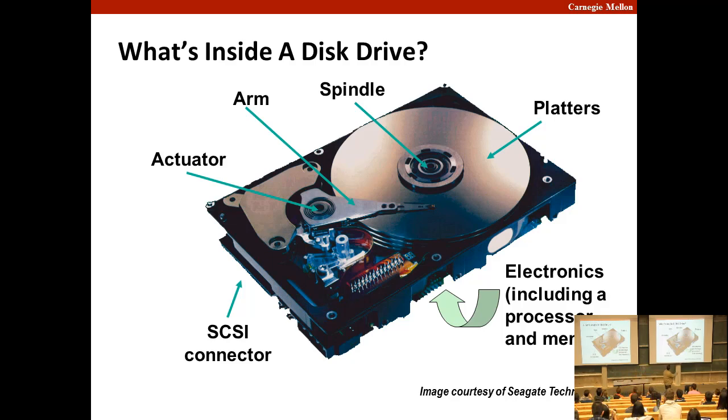The only thing I want you to get from this is that these are actually mechanical systems. The disk actually has to spin. The heads actually have to move. This takes time, okay? These heads are stopped. The disk is spinning under them. Now I have to energize that motor and swing that disk head. I have to get past the moment of inertia, get that disk head moving, and now I have to stop above where I want to stop. Hit the brakes. And now that I stop, there's a natural tendency toward oscillation. Any mechanical engineers in here?